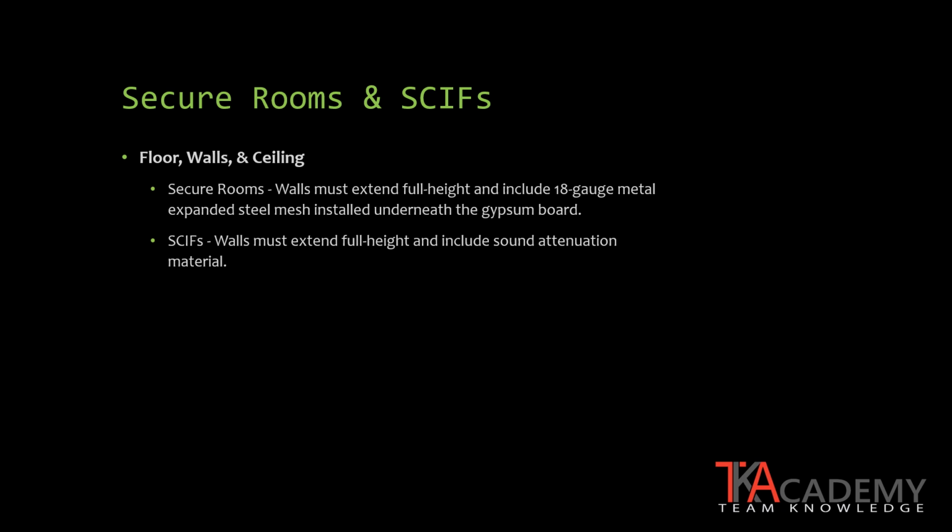For SCIFs, walls must be the same, extending the full height, but since SCIFs are primarily used in processing information, the sound attenuation of that wall is of utmost importance. SCIF walls must be built to a sound level class 3 or 4, which equates to a sound transmission class, or STC, performance rating of 45 or 50.